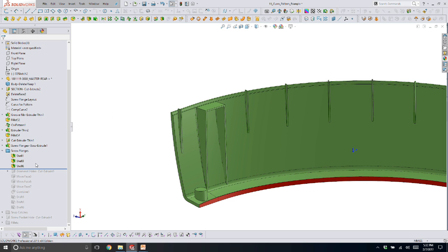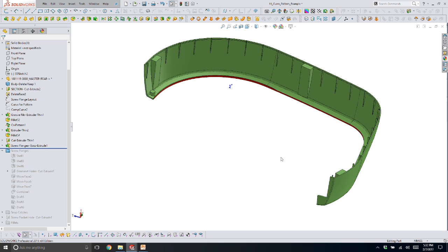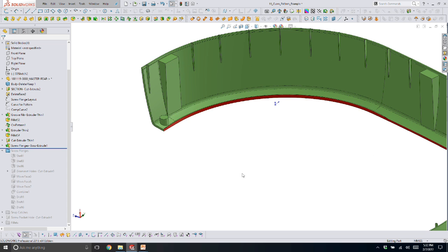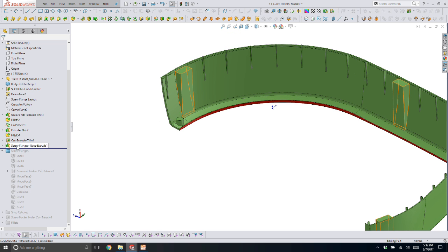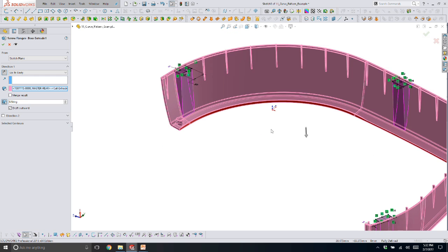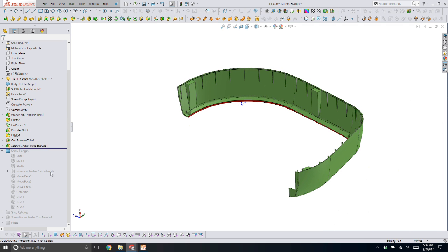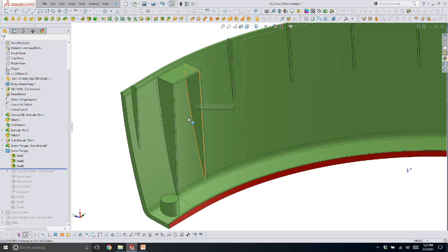So here I've used a single up-to-body extrude to generate 3 of these undercut flanges that'll have a little grommet going in here that will be used to attach these parts together. And this is just a single sketch on our plane. We're going up-to-body like I like to use. So I now have 3 separate bodies, and now I can go in and shell them. And so now I remove all the other stuff.